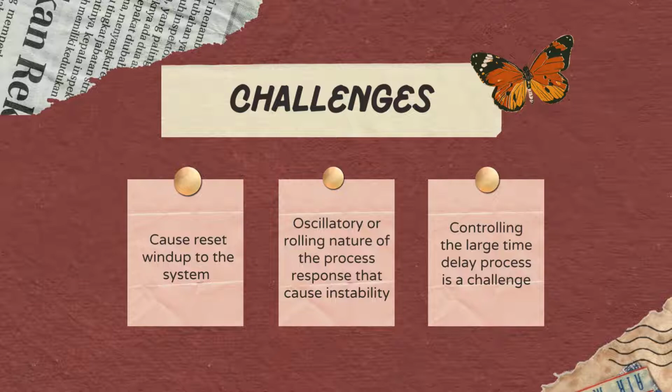And lastly, the challenge is to control the large time delay process, as the time delay acts as a barrier to a quick closed-loop response if the time delay is significantly more than the process time constant.